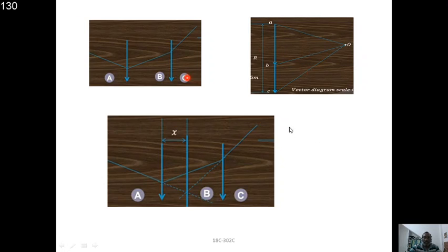These types of drawings are known as the funicular polygon method or area polygon method. Here, what these arrows represent are scaled areas. Hence it is an area polygon. This is an area polygon, and this one is the funicular polygon. By drawing these area polygon and funicular polygon, you can obtain the x bar value.